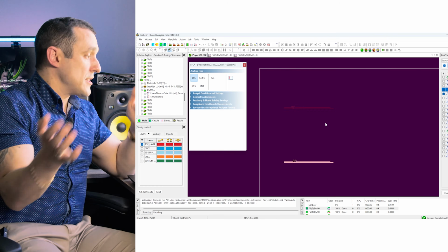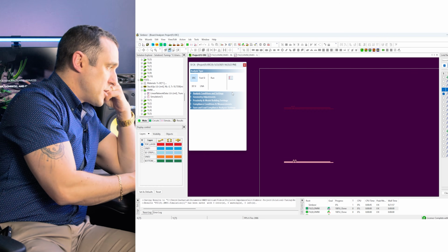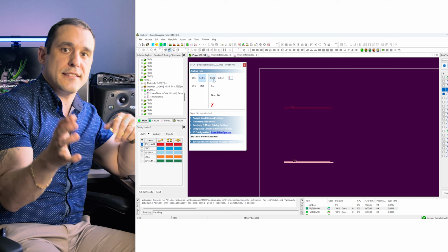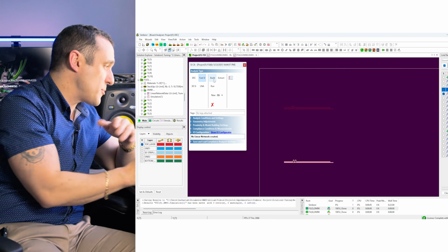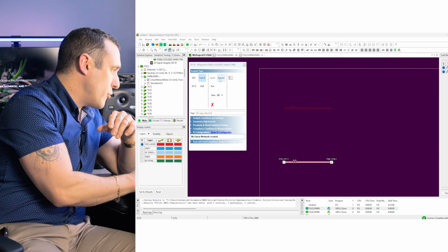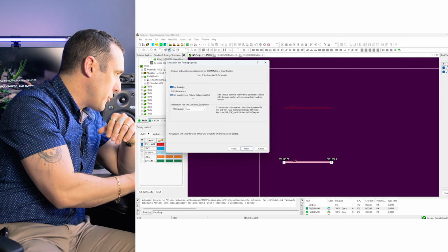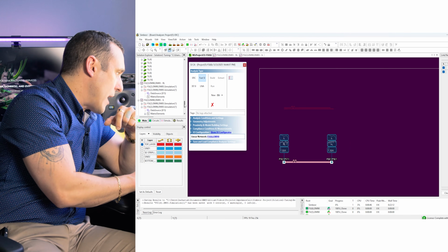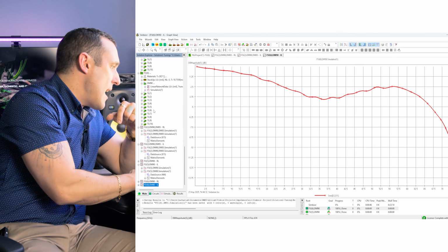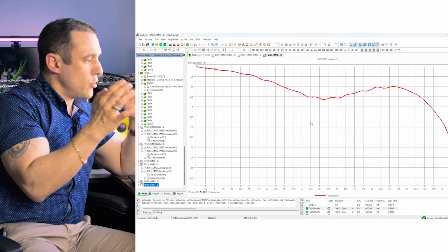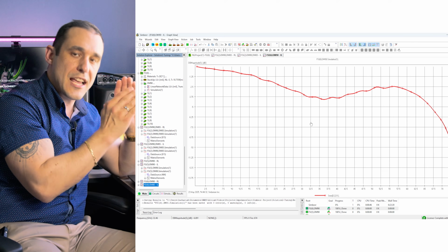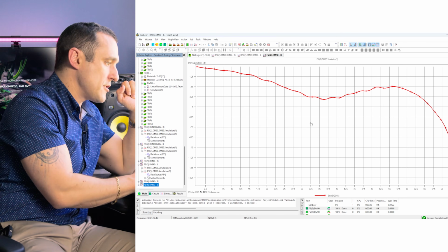So now let's look at what is the mode conversion S parameter for this interconnect. So first I'm looking at the pair of traces that have the narrow spacing. And if we go through, we build a quick simulation, we just click through the wizard, go ahead and hit finish. We'll go ahead and we'll grab the insertion loss plot. And just for comparison, I want to put the common mode output differential mode input S parameter here on this insertion loss plot.